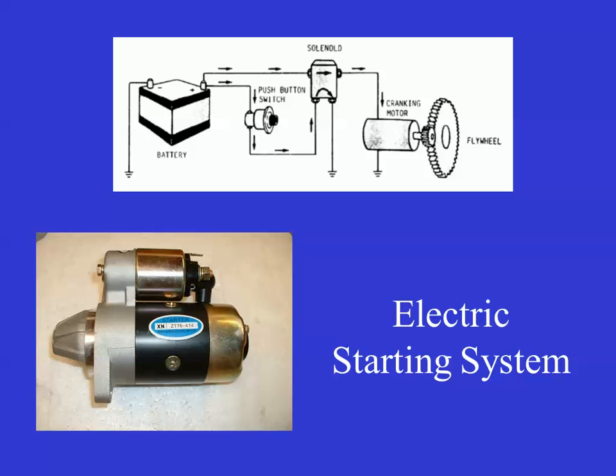Sometimes on your car, by the way, when you try to start it and you hear a buzzing noise, what's going on is your battery voltage is low, and the solenoid uses a magnetic field. If the voltage is low, it doesn't have enough oomph to pull the solenoid in, and the solenoid will come in, drop out, come in, drop out really rapidly and cause that buzzing. That's an indication that the battery is drained and does not have enough voltage.